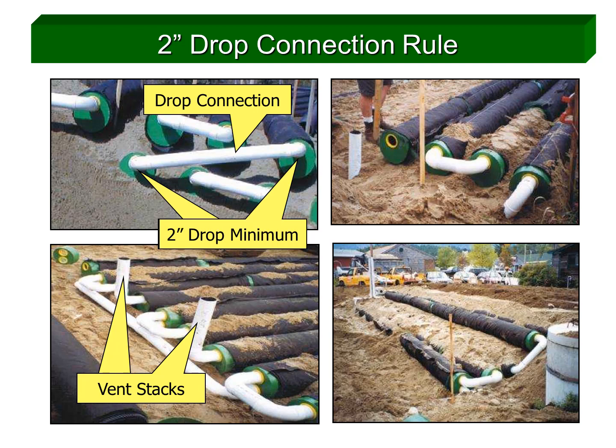Also notice that at the end of each serial section is a vent stack. As with single-level fields, multiple vents can be manifolded and brought to 3 feet above the surface as a single stack. It is also acceptable to bring each vent stack to the surface separately. It's important to make sure every length of pipe is vented properly. A common mistake is to attach the vent to the upper level rows and not the lower level.